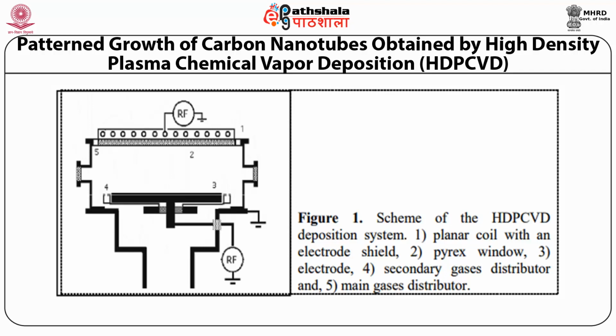The vacuum system is formed by a turbomolecular pump with a nominal outflow of 400 liters per second, and an auxiliary mechanical pump. The minimum base pressure that the system can reach is 2.1 × 10^-7 torr.